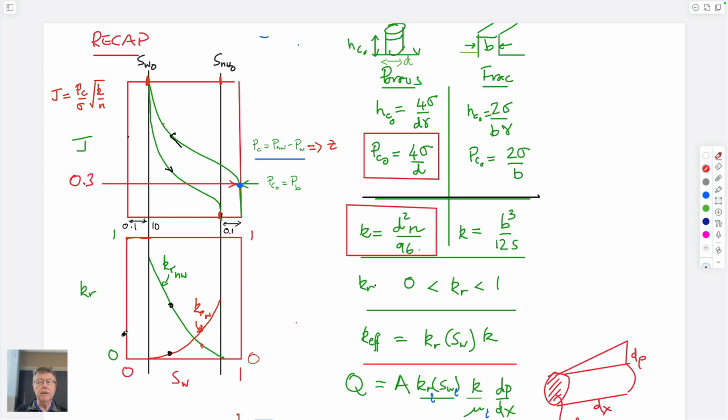And when we talked about solving numerical models that address these multiphase flows, the fact that we have to solve 2 equations to close the set of 4 equations for 4 unknowns. And the 2 closing equations are that saturations add to 1, and that the capillary pressures in the 2 fluids must conform to the capillary pressure saturation curve. So that's our reason for doing it. Our motivation was much simpler than that, though.